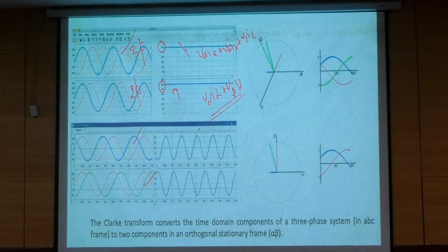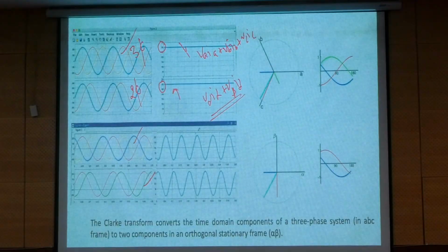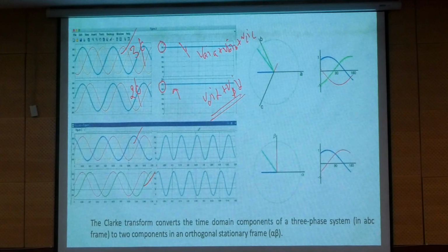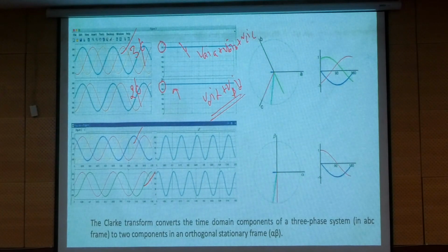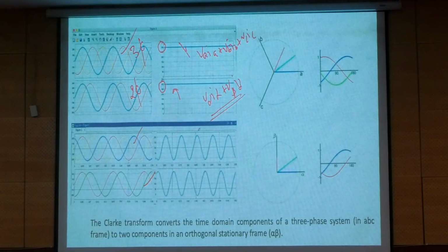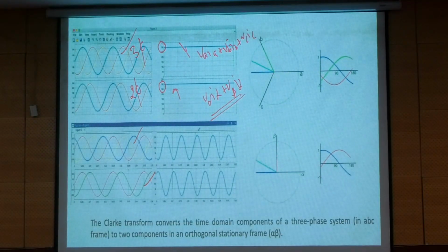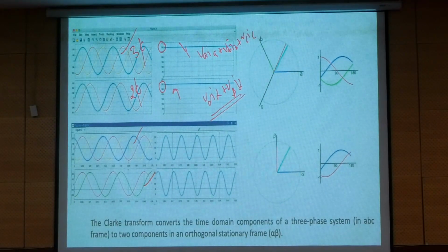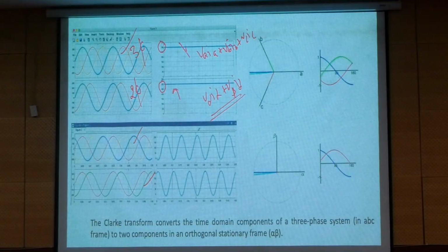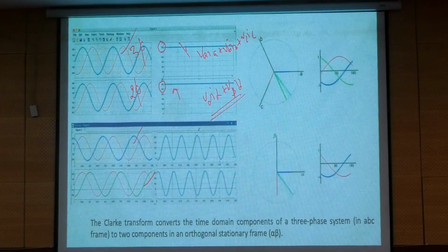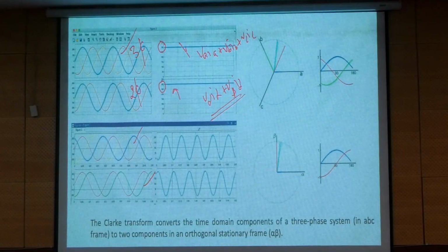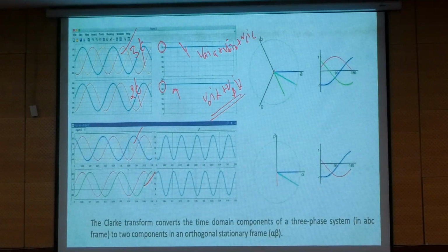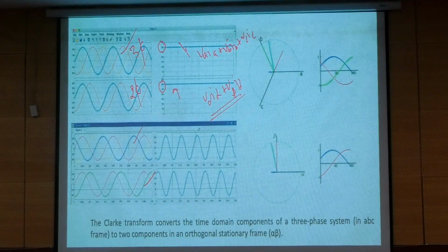In case 1, power is not changing, net power is constant, but if you verify individual peaks, it is getting affected. Now, in the case of the magnitude invariant condition, the three phase peak voltage and two phase peak voltage, V alpha peak and VA peak, both are the same. Nothing but magnitude is not getting affected. For phase power it is also checked, it is not changing. But if you add net power, it will change. Net power is different, 1.5 times less.